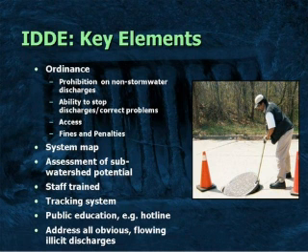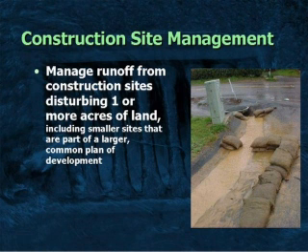And now I'm going to turn it over to John real quick, and he can talk about construction. Thanks, Nikos. Yeah, the one major element that's probably a challenge for most communities is managing erosion and sediment from active construction sites. Phase 2 specifically mentioned all sites disturbing 1 acre or more, including, in the fine print there, sites smaller than 1 acre that are part of a larger common plan of development. We should note this is separate from the NPDES permits that are issued at a state level. This is for the municipal programs, municipalities running Phase 2 to implement their own program to control construction sites.